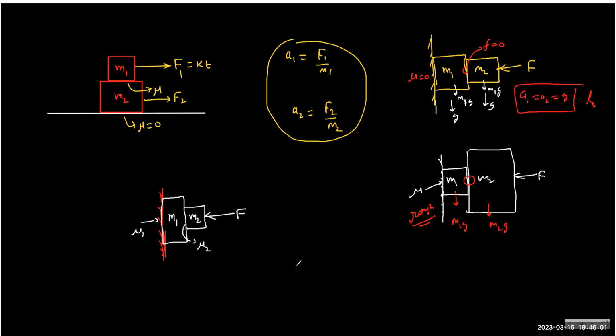You assume no friction to get the tendency first. And therefore, in this case, the FBD of M2 will be M2g down, and the friction will be F upward. And therefore, the FBD of M1 will be F downward, M1g downward, and of course, F2 upward. I mean, let's call it F1. And then you will solve beyond this point. You will check whether F1 max plus M1g is exceeding F2 max or not. You can't just write the laws of motion.